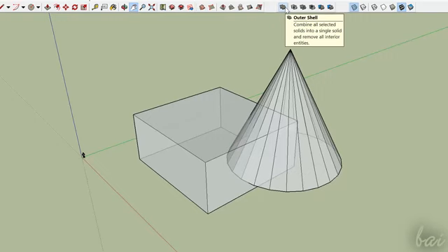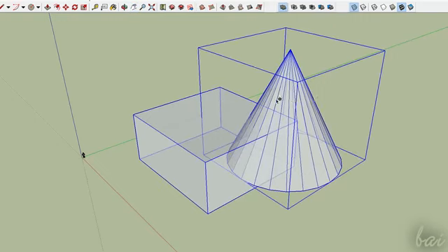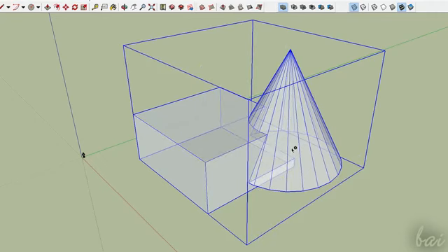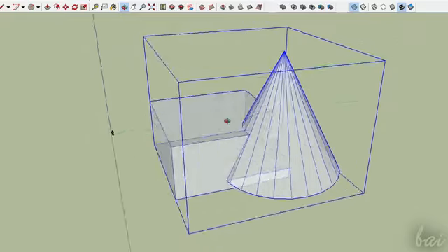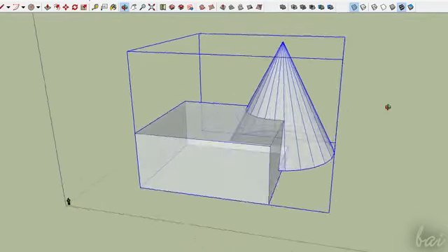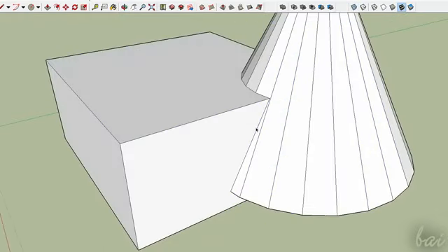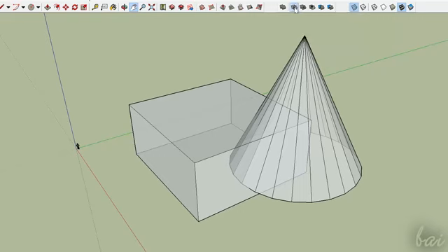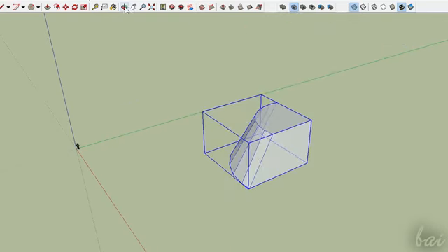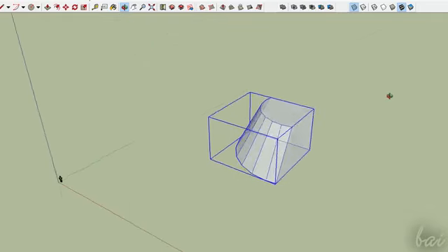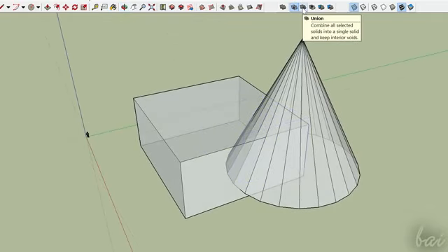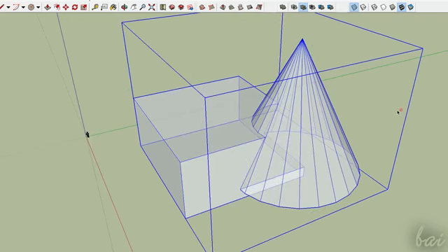If you enable outer shell and select the two solid groups, SketchUp creates a final solid that is the union of the two, removing all interior faces and contours not visible outside. Plus, external contours will be added. If you use Intersect and you select the two solids, you will obtain just the solid part that is overlapped. If you use Union and select the two solids, the final solid will be the union of these two.